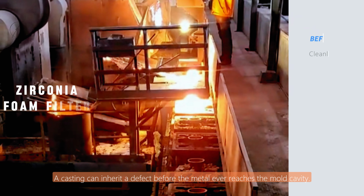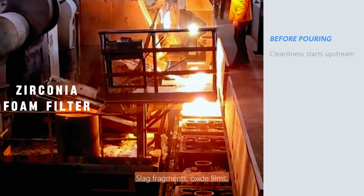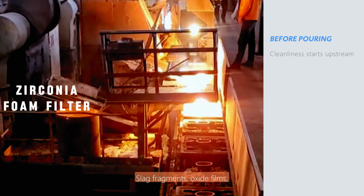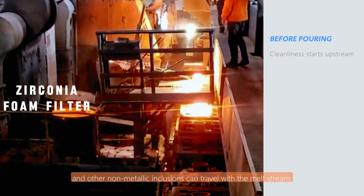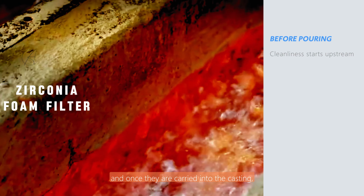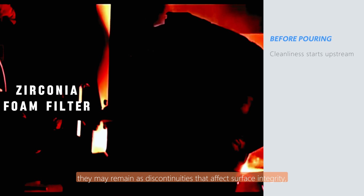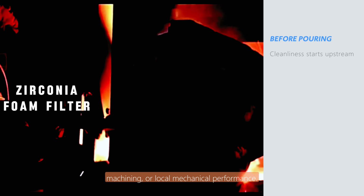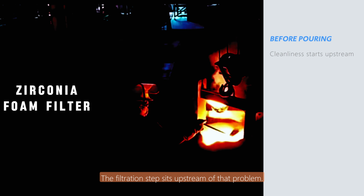A casting can inherit a defect before the metal ever reaches the mold cavity. Slag fragments, oxide films, and other non-metallic inclusions can travel with the melt stream, and once they are carried into the casting, they may remain as discontinuities that affect surface integrity, machining, or local mechanical performance. The filtration step sits upstream of that problem.